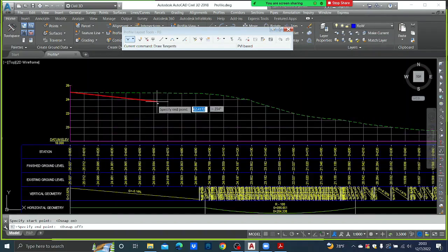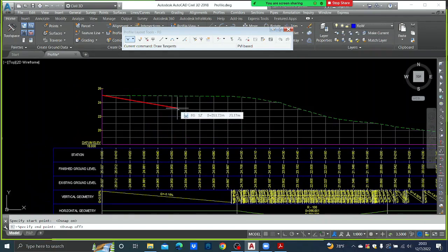So when you are going to put it, remember your curve length is 50, that you have to keep in your mind, right? If it is 50, definitely the length difference between two IP points should be greater than 50. Understood? Otherwise you can't have it. So you will understand when I'm doing that.